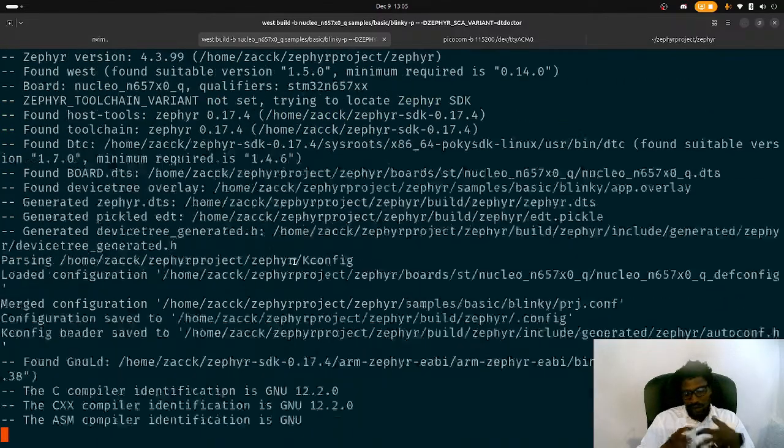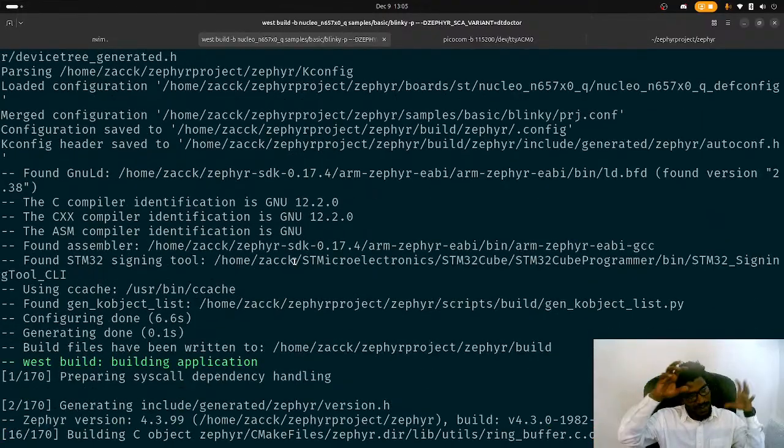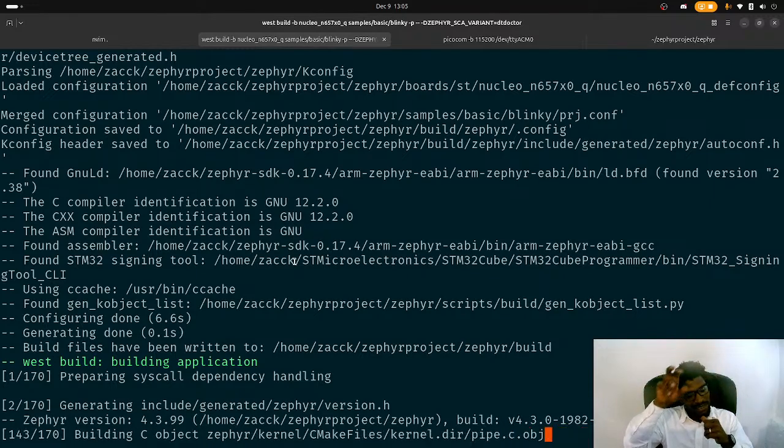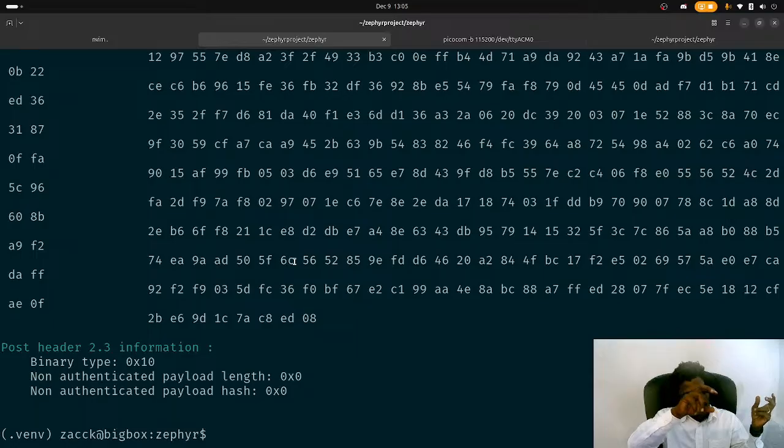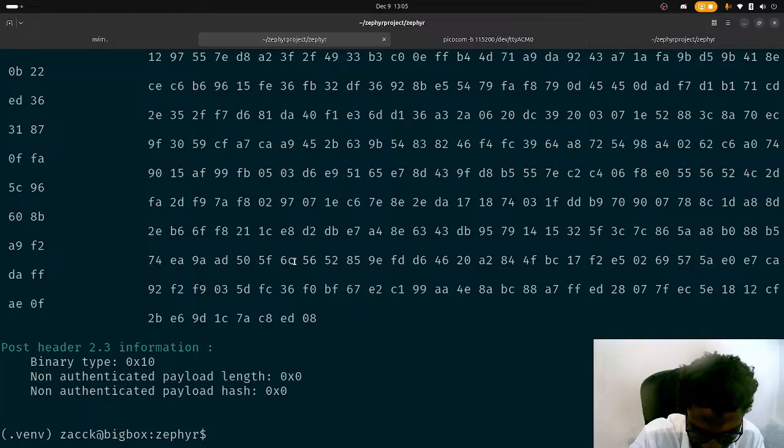So okay, the problem ended up being we were missing the SPI driver. Our GPIO driver needed the former driver to get SPI, and then the former driver was failing, so our GPIO driver wasn't getting activated. So with this, we should actually get something going. I'm hopefully looking forward to getting that error that says pin 0 is being configured, then I think it's working.